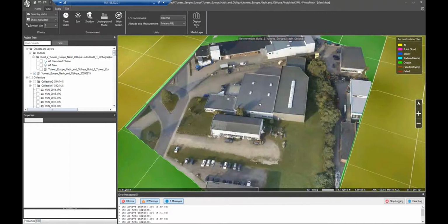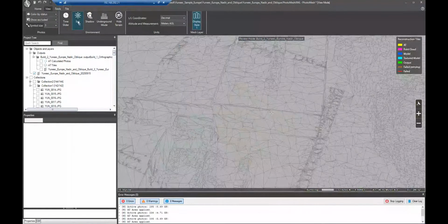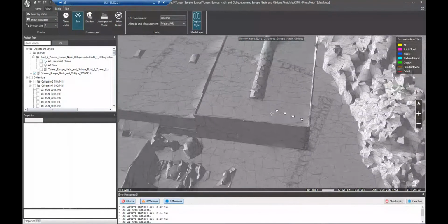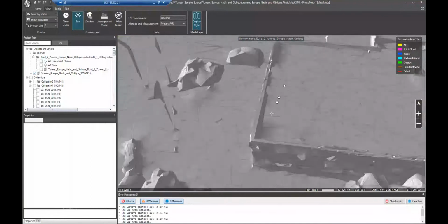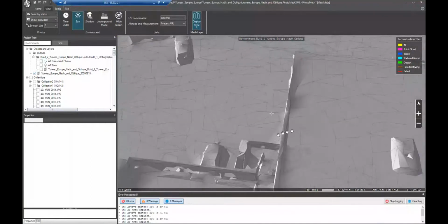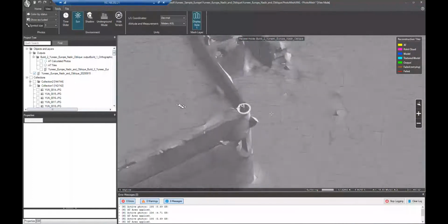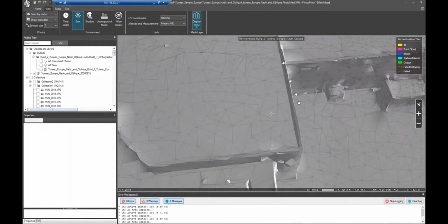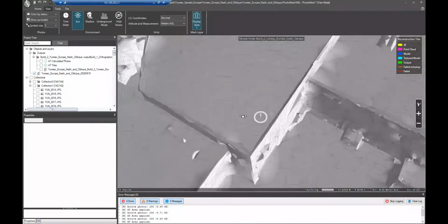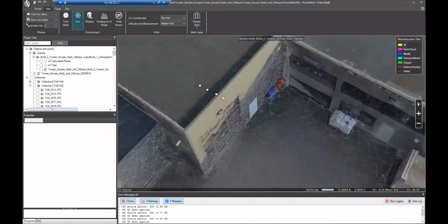Now, one thing that gets done during the 3D extraction process is we extract the edges, direct extraction of linear features. So you can see wherever there are corners or straight lines, they have a connection of multiple features that then enable the edge to be much crisper, very straight. And that can also be visualized with the triangles on top of the mesh.